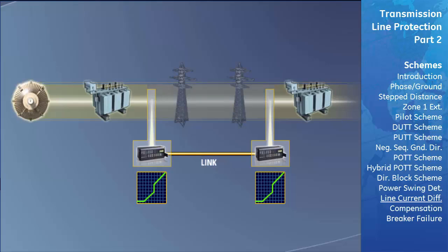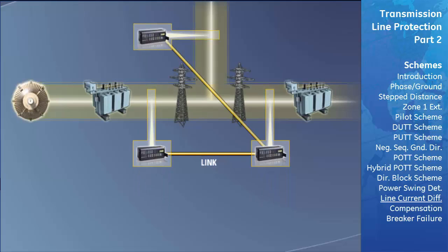The L90 relays support both 2 and 3 terminal configurations. The relays in a 3-terminal configuration will behave in the same fashion as the 2-terminal configuration, with each relay making its own decision as to whether it will trip. In this way, all L90 relays are said to act as masters. If there is a failure of one communication channel path, the relays will automatically switch to a backup master-slave mode. The relay that is still in communication to the other two relays will be the master, and the other two will switch to slave mode.